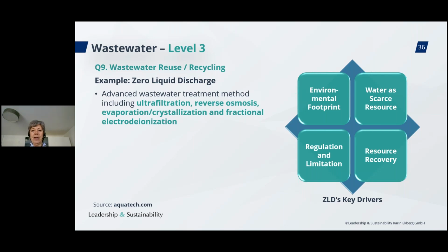So you can reduce the sludge volume very much with filter presses, etc. But when you really need to make it into a dry solid, then the energy demand is very, very high. For evaporation, you will be using so much more energy. Therefore, it's not always technically feasible or even economically feasible to take this final step.